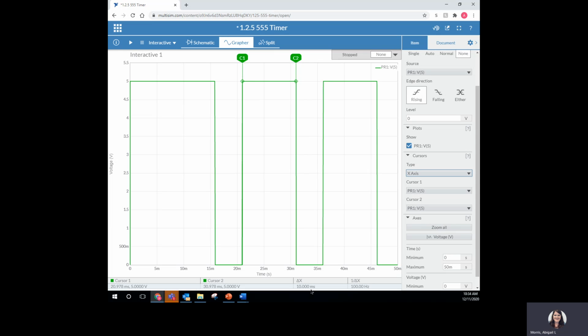So I'm going to use the equation, time high divided by the period, capital T, times 100%, to calculate my duty cycle. Make sure that you put your units on question 2 for full credit. And that is it.